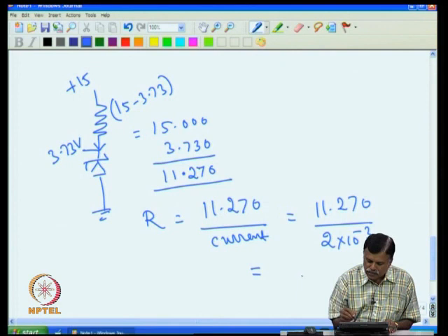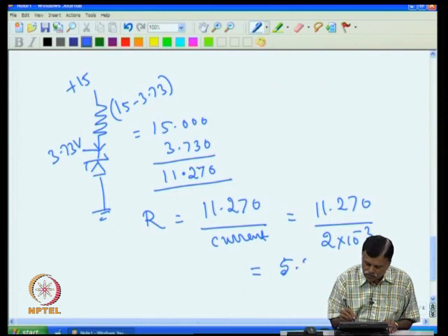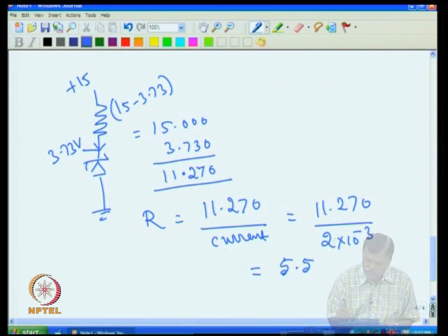If you convert into resistance, then you will get 5.6 K resistance. If you do this division, you will get 5.6 K. Now, if I look at the nearest value that I can put, 5.6 K resistance. If I put 5.6 K resistance, then I know approximately 2 milliampere current is maintained through the sensor. So, I will put here 5.6 K.